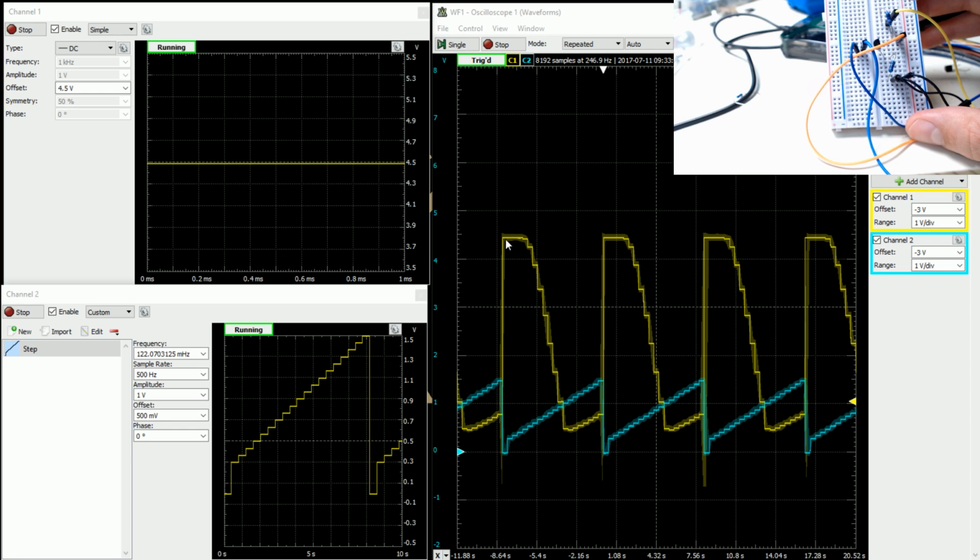So the 4.5 that's up at the top here, that is basically what the rail is set at, right? And I can move that up even. I could set that to 5 volts instead of 4.5. You'll see it move up on the next sampling. And so what we see, though, is basically the yellow represents how much current is flowing through here, right? So when there's 5 volts, there's no current flowing. When there's 0.7, that looks a little bit low actually. That is a little bit low.